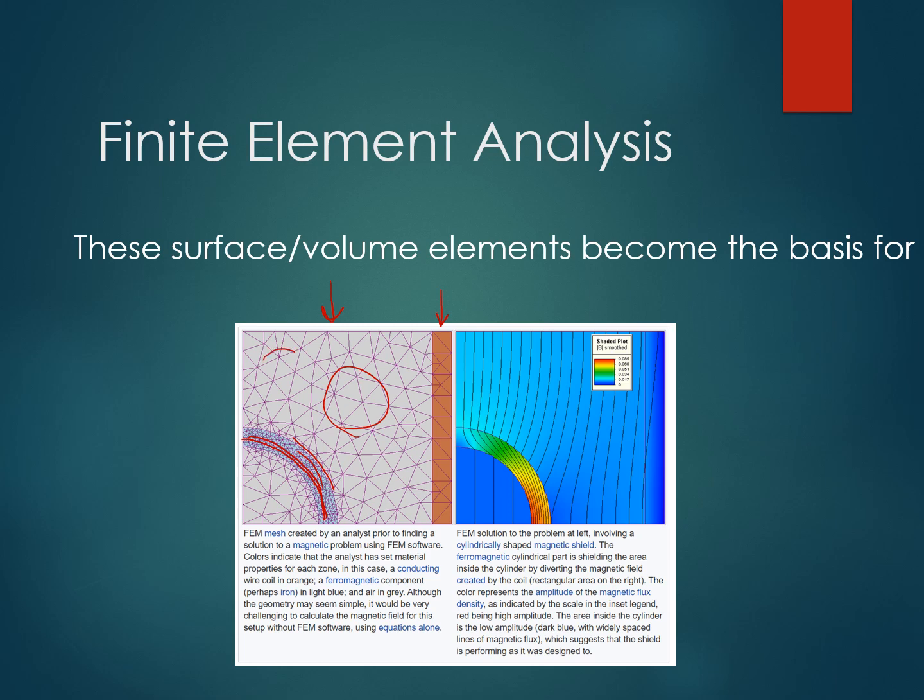Whereas out here in just the medium of air, we have a relatively coarse mesh because those lines should be nice and straight. We see that the visualization, the result of this is that we see these magnetic field lines traveling through that are always going to be perpendicular to the flow of current through a wire. And you see how this choke or inductor guides these field lines alongside of it, such that on the interior we get no change in those directions.